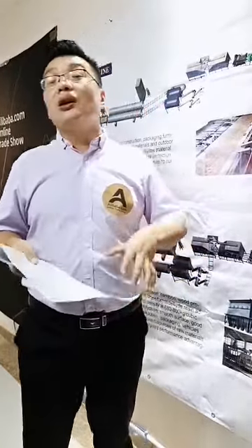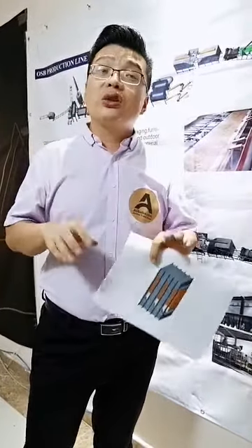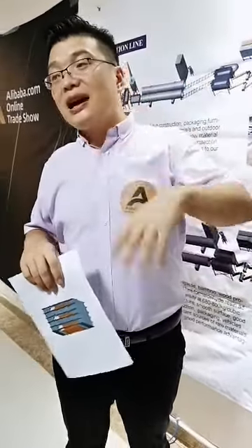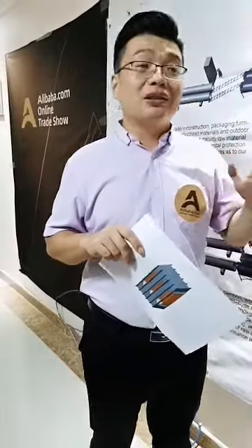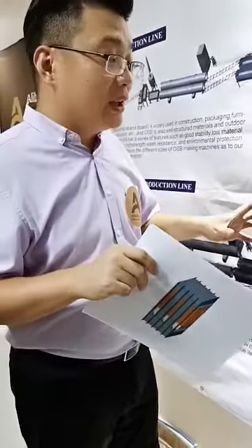Because for particleboard, we need more pressure to make it more dense, and also more heating oil circulation to get a high temperature and quick press and quick reaction of the glue. So we need higher pressure and higher temperature to make the particleboard form into the final product quickly. That's why we need the big one, and also a high pressure one.